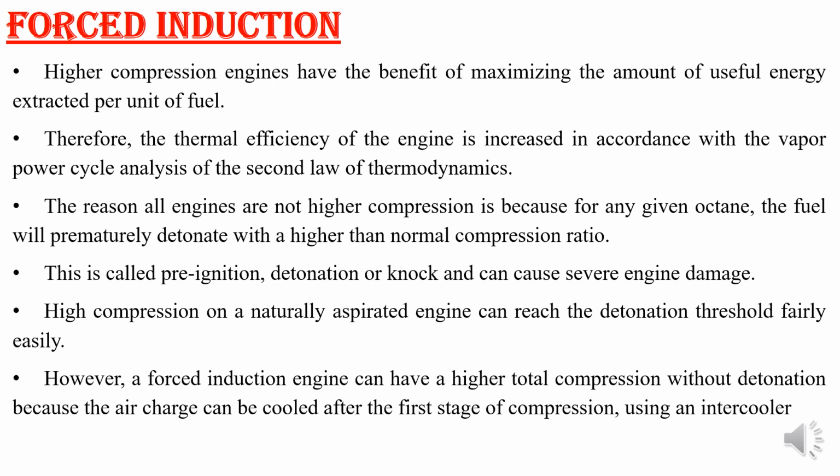That means one device we are using, like a compressor. What it does is increase the pressure, and after increasing the pressure, the temperature also usually increases. So we place one device, an intercooler. What it does is reduce the temperature and bring it back to the normal condition without losing the pressure. Hence the intercooler is placed after the compressor, so that the temperature can be the initial temperature and the pressure can be higher, that is the boost pressure.